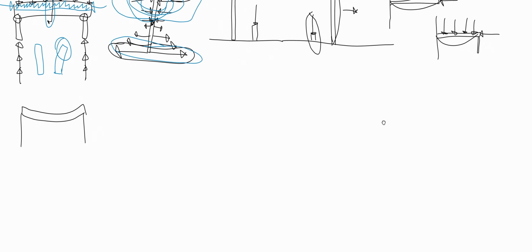Most of the time, we are actually just going to be concerned with members deflecting too much. So if I have a wall on this side and a wall on this side and a great big beam spanning across, and this is a beam that's creating a ceiling line to a vaulted ceiling or something wonderful, pretty. And there's going to be a big edge here that everyone's going to see. Well, I can't have this beam be loaded and put a big belly in the bottom of the beam because that's going to be noticeable. If the distance here was, let's say, 1 inch or something, depending on how far that beam will bend downward will change if that's acceptable or not.